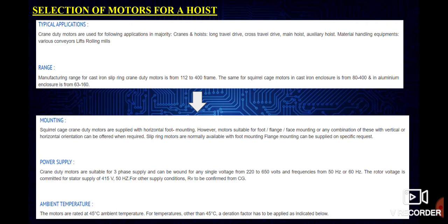Now for ambient temperature, the motors are basically rated at 45 degrees Celsius ambient temperature, and for temperatures other than 45 degrees a derating factor is applied.